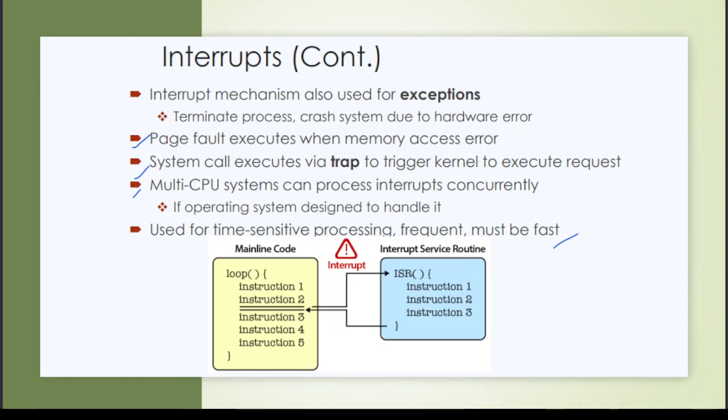But between 2 and 3 we have an interrupt, or interrupt service, that must be served. When the CPU encounters it after the second instruction line, we go to an ISR function and it is executed.